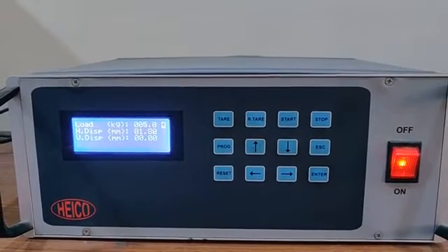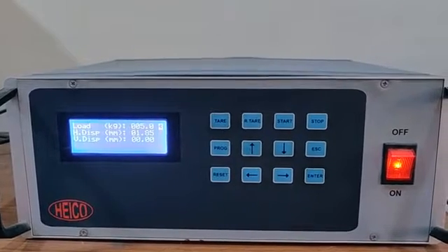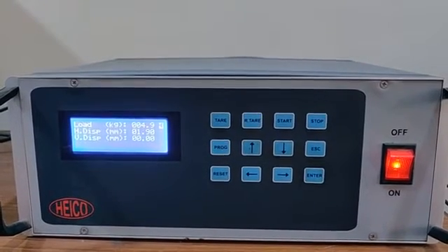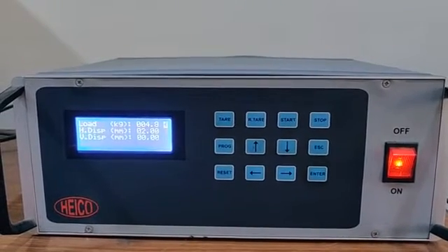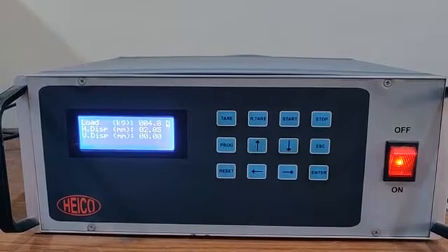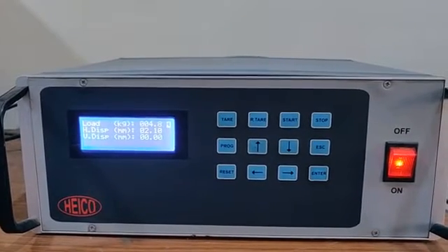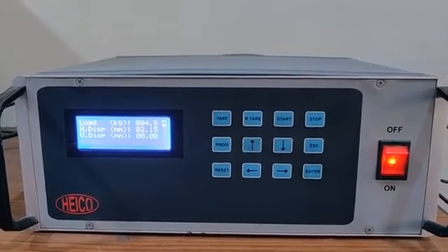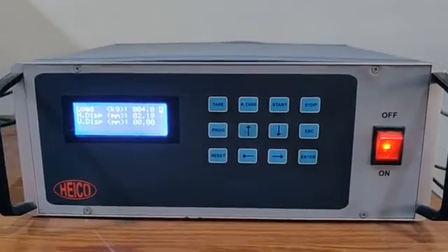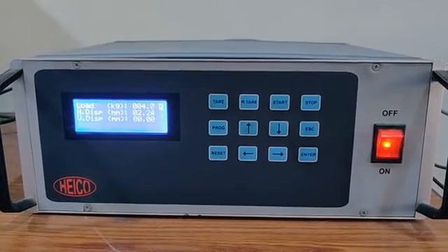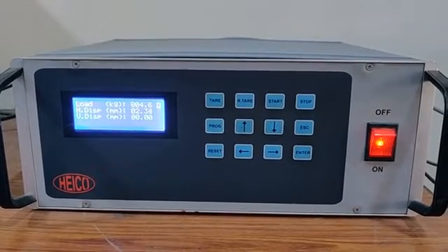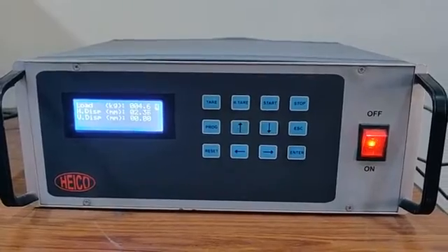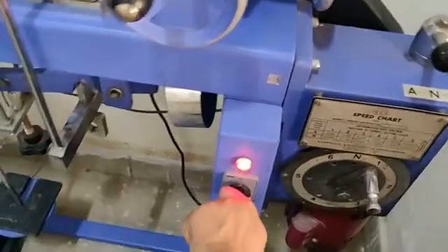Load is still applying, but the displacement is increasing while the load is not increasing. If it increases after 5, then we will note it down, otherwise we will take that as the final load. I think it is going to decrease, so we will take 5 as our final load, and we will divide it by the area, so that the shear stress will be calculated from that. So that will be our final load. And now we are going to switch off this.